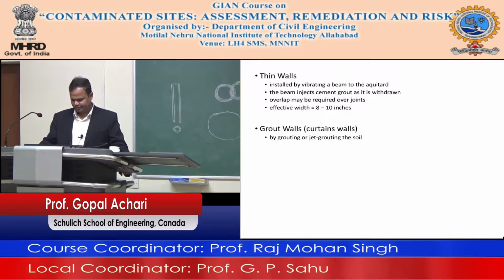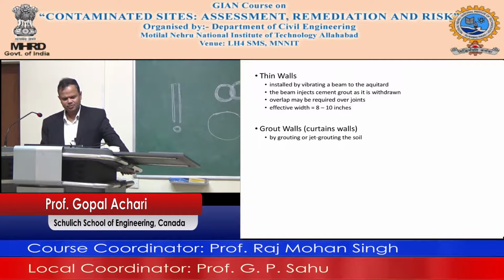On top of that is what is known as a geonet. On top of that is a geotextile, and basically this is a drainage layer. And then you have rocks. You have a pipe here. The pipe is used to carry the water out, and then the top geotextile, and on top, sand and then fill.